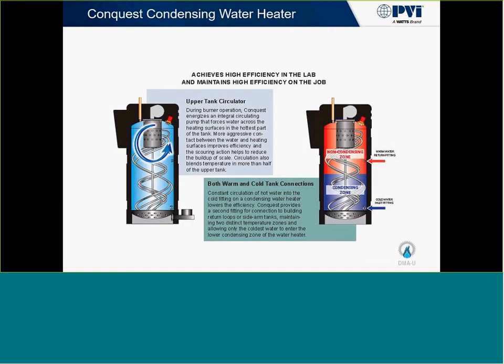So another thing that you'll notice with these type of designs is our return fitting is at a midway point on our tanks. If you remember on the boiler tank design or any other manufacturer of water heaters, they bring their building return into the cold water feed of their water heater or boiler, which is preheating the water going into the system.